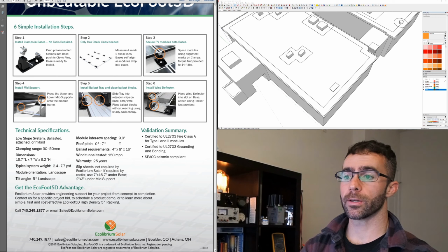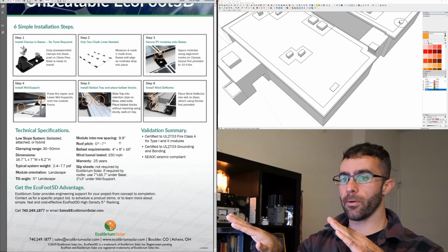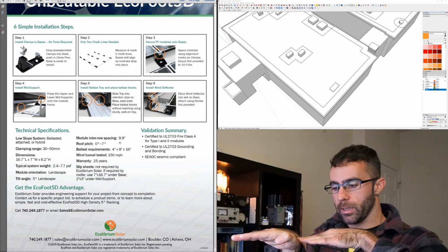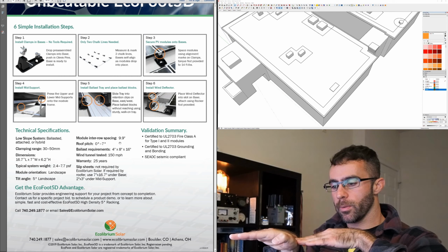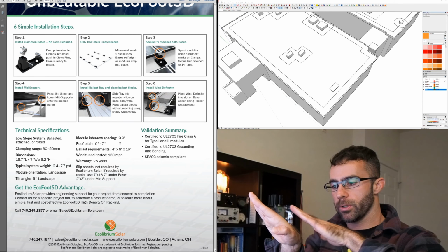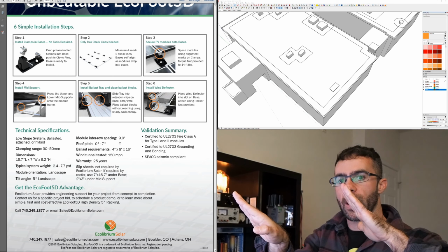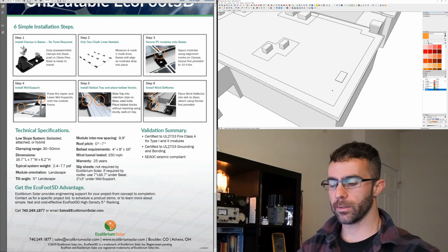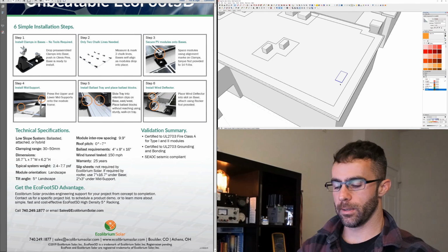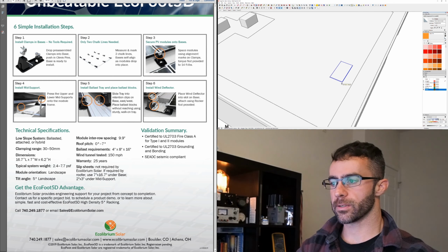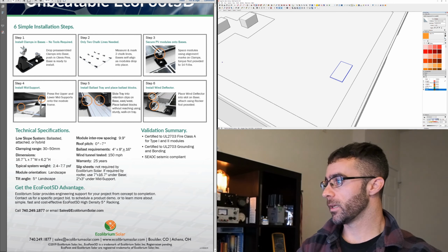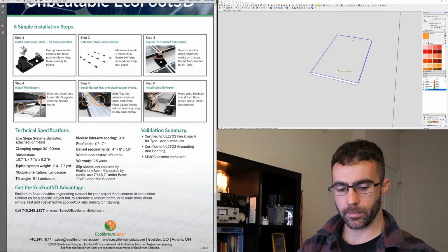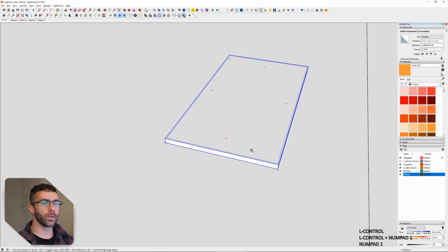There we go. We could have tried to calculate it based on the orientation of the sun, and as you get closer, you can have your modules butted up to each other, but as they start to pitch, they would shade, so you need to start spacing them out. That's inter-row shading. I can go into that in more detail if people need, but for the sake of this exercise, we're just going to go with what the data sheet says, 9.9 inches. So we go into our module. Let's make this bigger.